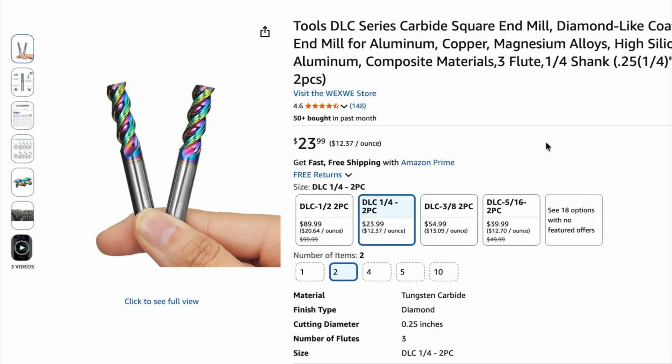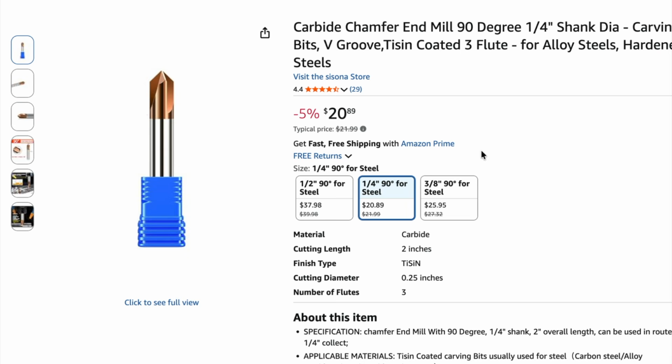So those are your end mills. You may want to throw a ball nose in here also, an 1/8 and 1/4. The machine comes with one. You're not as likely to break a ball nose as you are roughing with a flat end mill. But anyway, those are your end mills. I would personally add another chamfer mill. You're not as likely to break a chamfer mill, so you might want to get a better quality one. The machine comes with an 1/8 inch. I'm going to go ahead and get a 1/4 inch also, because I'm likely going to be using bigger tooling anyway with the 1/4 inch collet in the spindle. So add a chamfer mill, maybe get 2 of these. You're going to want to put chamfers on your parts. This is pretty critical, and this one's going to stay loaded in the tool changer at all times in my opinion. So these are our cutting tools.